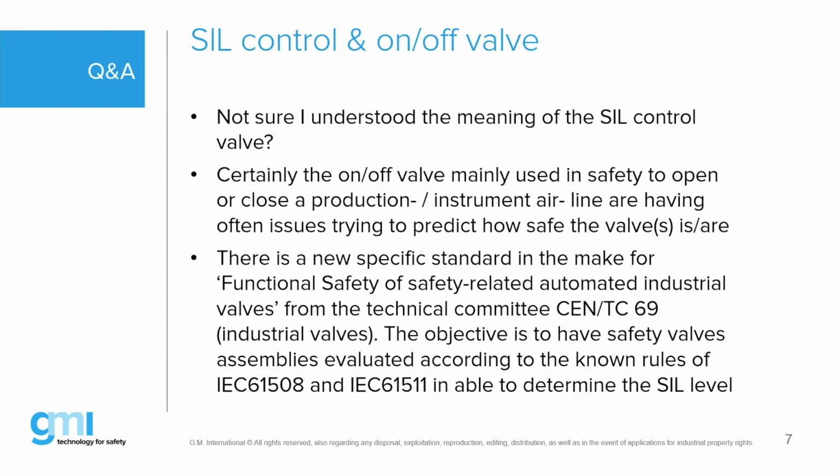But let me also address something you said earlier that might have been misunderstood. Because we are a component manufacturer, we offer our customer a certification. It's a piece of paper that says certificate in German. But what that means is that the product is compliant to a standard and is supposed to do a specific safety function. Of course, you correctly said it's not the product that is certified, it's the loop, the SIF, that needs to be certified. Correct, Paolo.